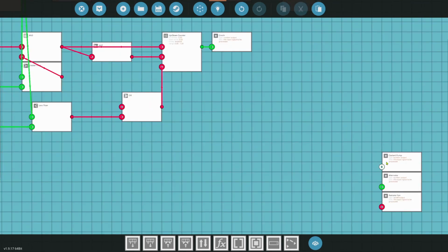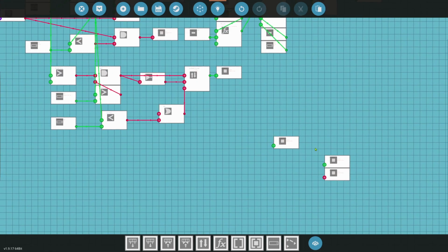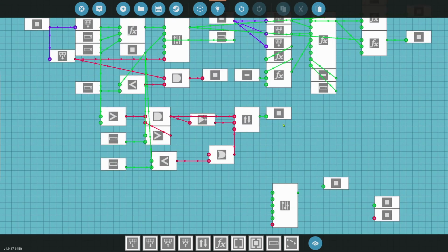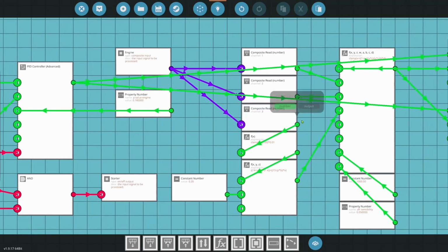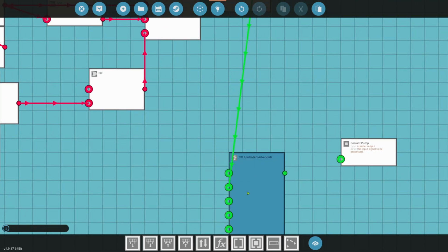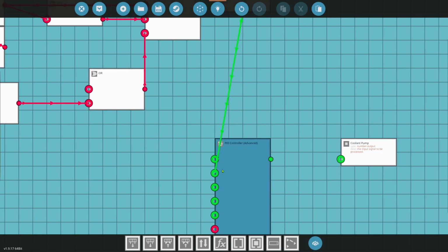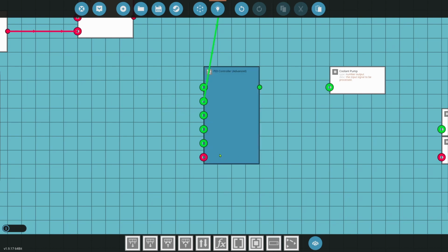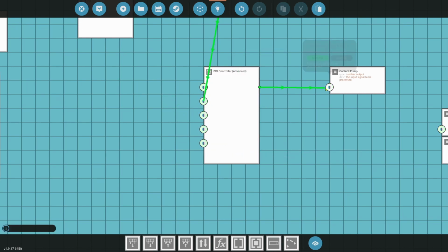All right, so the next thing we're going to do is coolant pump. We're actually going to do this the simple way. There's 2 ways to do this. One, you could take a PID, and you could plug in the value here, the 3 value. That is our temperature, and you could put that as your process variable. And then you could set it to say 100 degrees, and then you could put in a separate p-value. You could turn it on, and it would only give you enough coolant pump to make sure the engine stays at 100 degrees, and that would make it so the engine theoretically could stay exactly at 100 degrees.